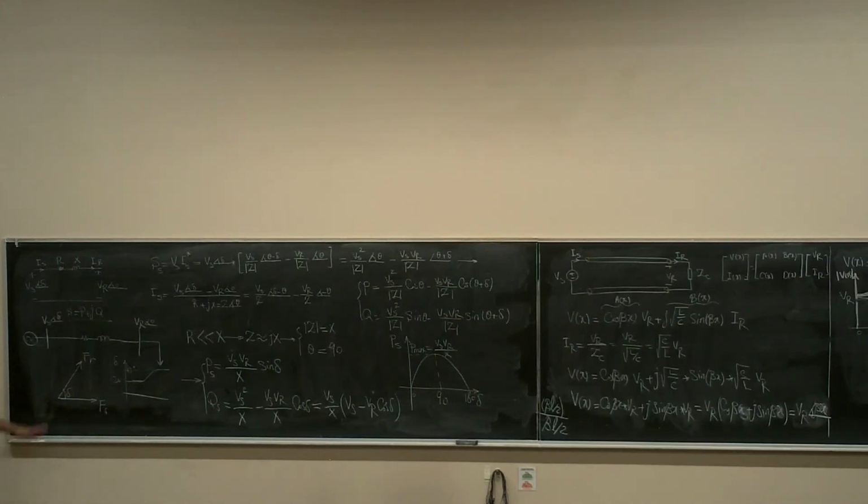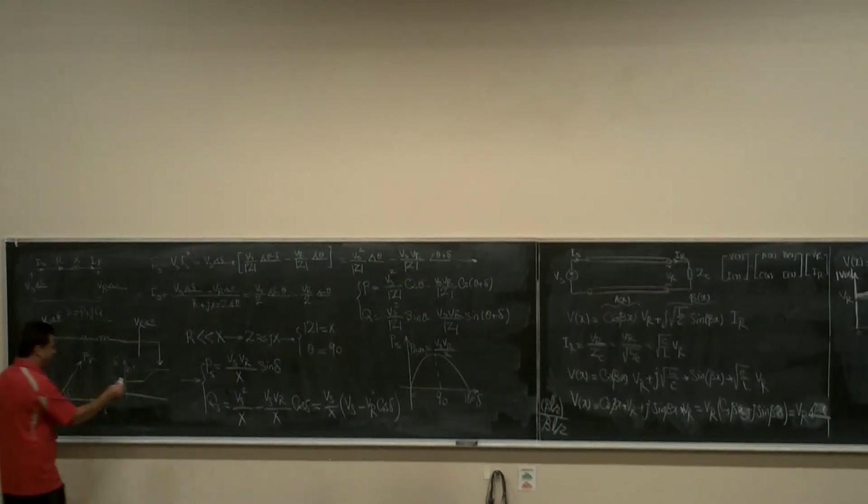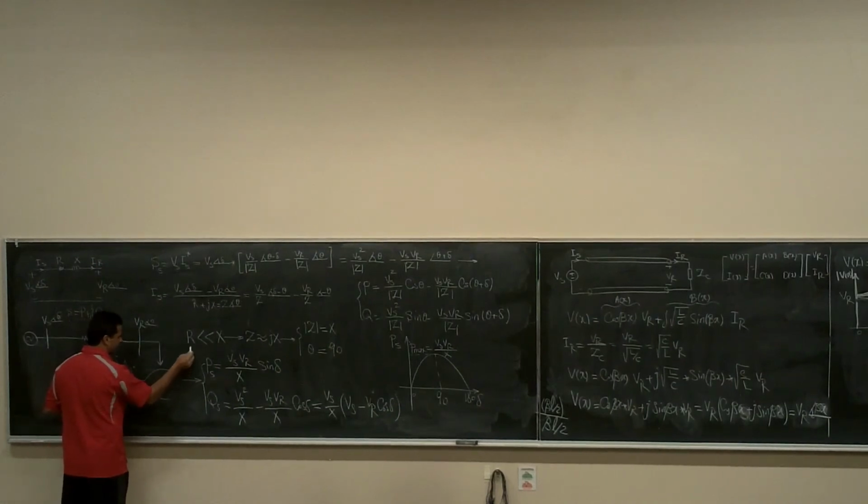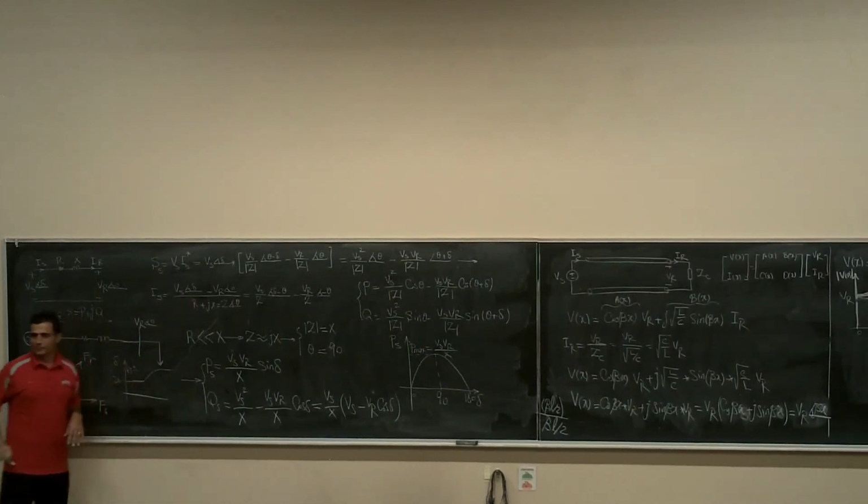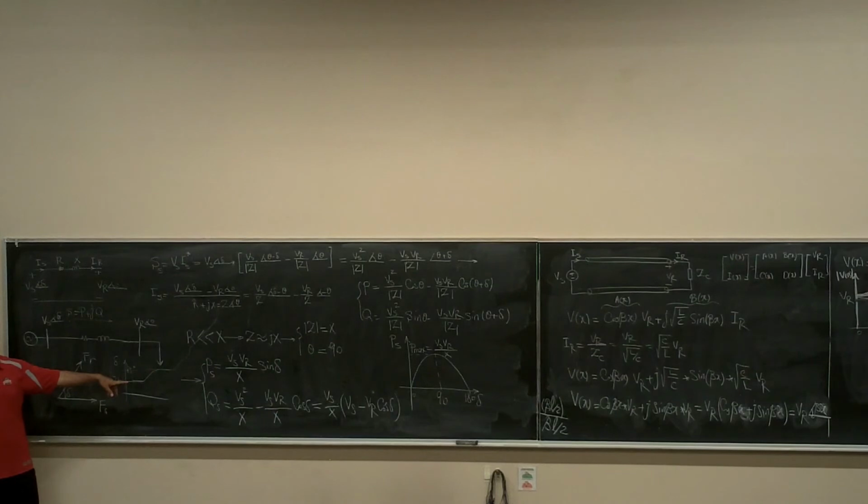What's going to happen? This poor guy says, I have to open this up more and more. But after 90 degrees, I'm not doing anything. After 90 degrees, it is getting worse and worse. What is going to happen? This delta is going to go like this. And as soon as you pass 90, not exactly 90, a little bit more than 90, and you cannot provide the load, you are done. Your system is going to get unsynchronized.